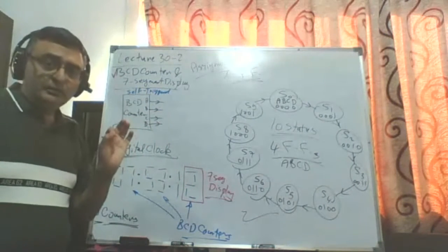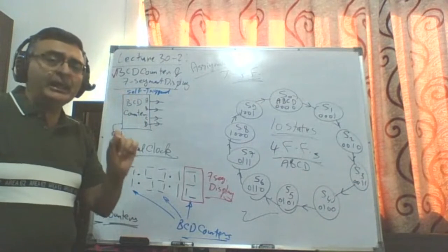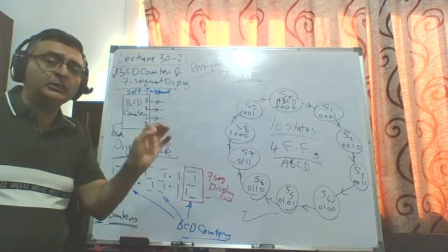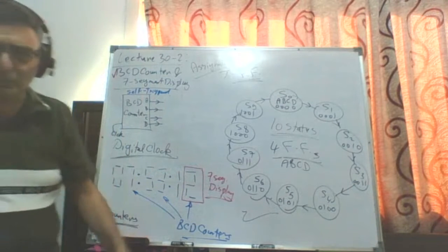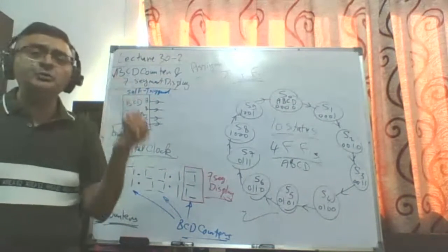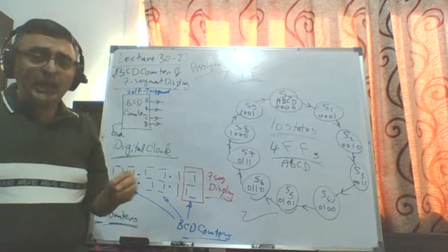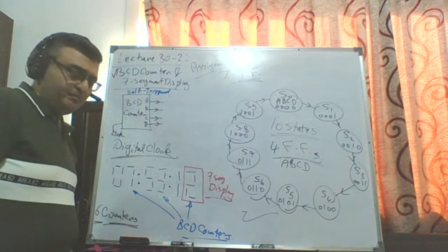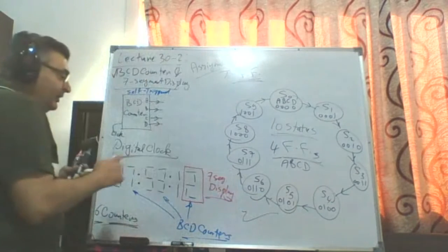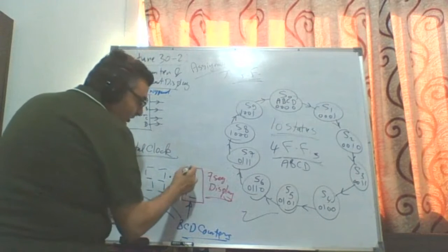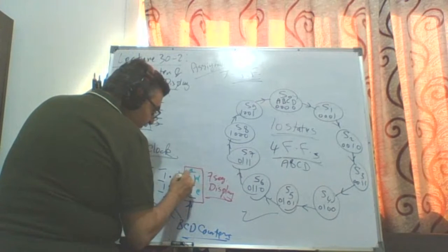By changing the value of each segment, I can display different numbers or characters. So first of all, that's why it's called 7-segment display. It's actually 7 LEDs. By lighting or dimming those LEDs, I can display the different numbers. Right now, if I give those LEDs identifiers or names, I will call them A, B, C, D, E, F, and G.